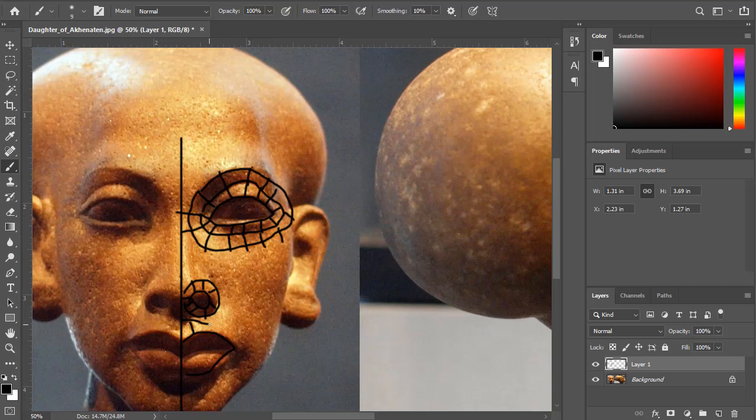And once we draw something in between these, we can actually connect them. Like so. Once we have these three different patches, all we need to do is extrude from all these things and then combine them finally to make the entire patch. Once we finish one side, we can make the mirror to the other side. So while working, we can check how the other side is going to look. This is basically the process that we're going to do in Maya.